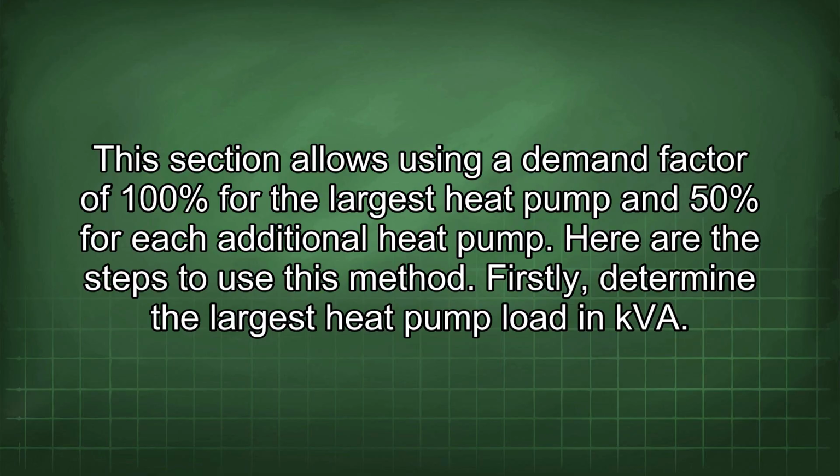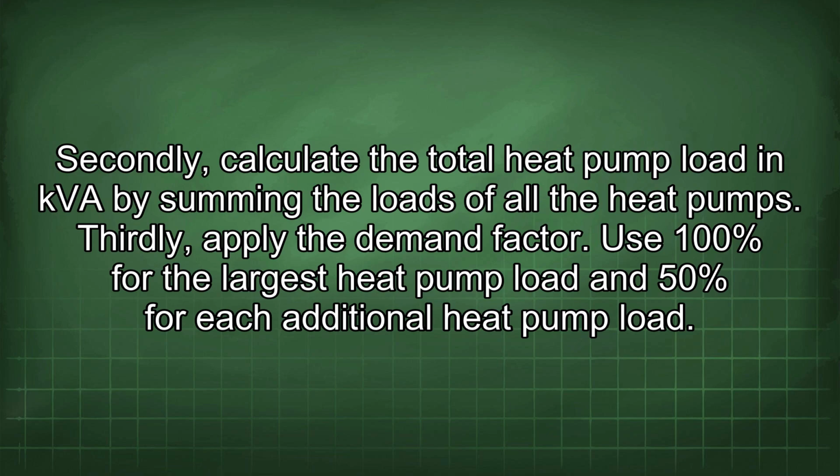Firstly, determine the largest heat pump load in kVA. Secondly, calculate the total heat pump load in kVA by summing the loads of all the heat pumps. Thirdly, apply the demand factor. Use 100% for the largest heat pump load and 50% for each additional heat pump load.